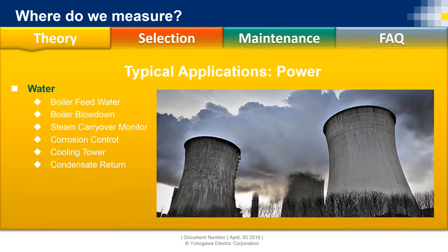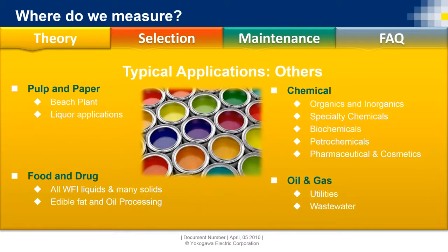Again, in power plants, you're going to have your boiler feed water, you're going to have your boiler blowdown. As your scaling increases, that conductivity value will increase to a threshold where it'll indicate, okay, now it's time to blow out all of the junk left over in our boiler drum. Cooling towers, condensate return, you're going to have conductivity readings. But those are just for more like water quality within a plant or a process, right? However, there are applications that go beyond just water quality.